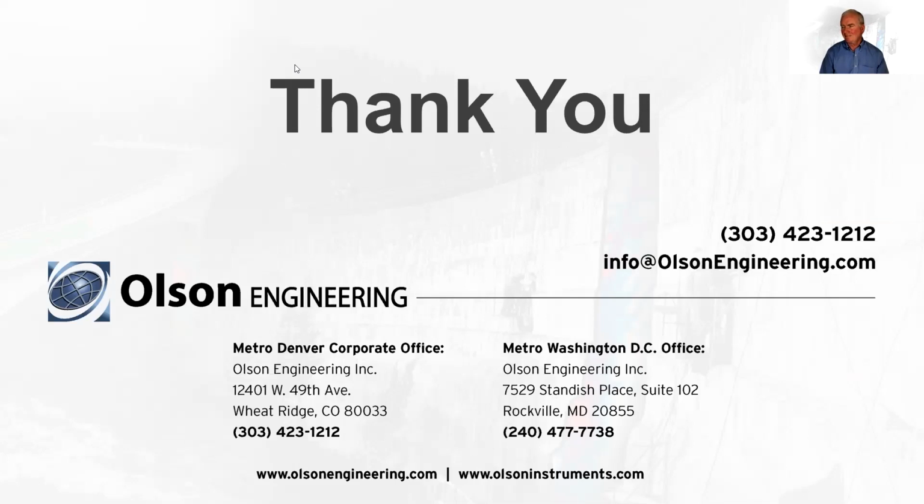So then the next question is, what is the accuracy of SASW and how do we avoid higher modes during processing? Well, it depends on what you're doing. You're definitely going to get some higher modes. The issue is that it's somewhat dealt with in the latest multi-channel analysis of surface wave software. Dr. Stokoe and Rosset put in a rough approximation theoretically for higher modes in the earlier WinSASW software that I learned on. And I've used the newer software a bit myself.